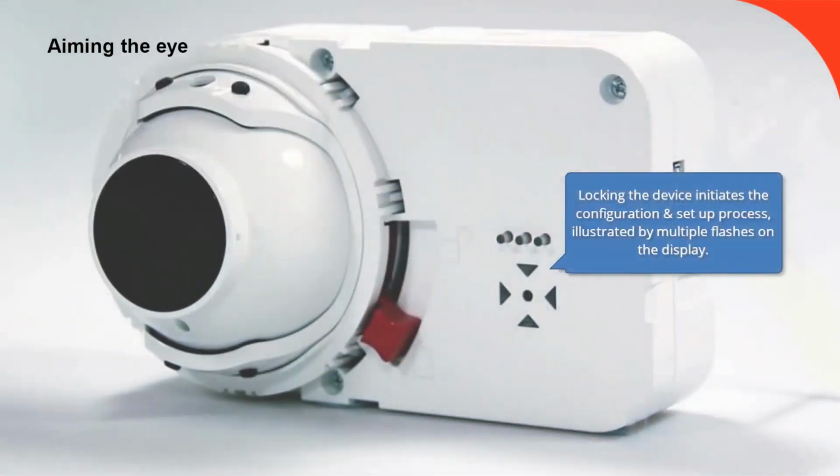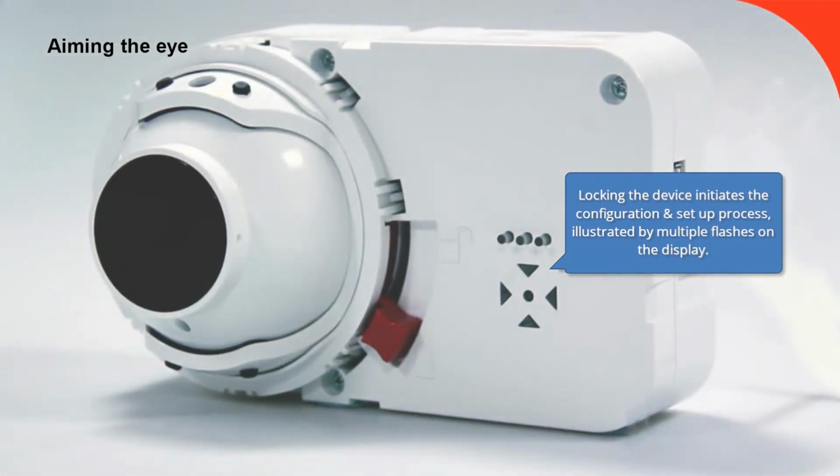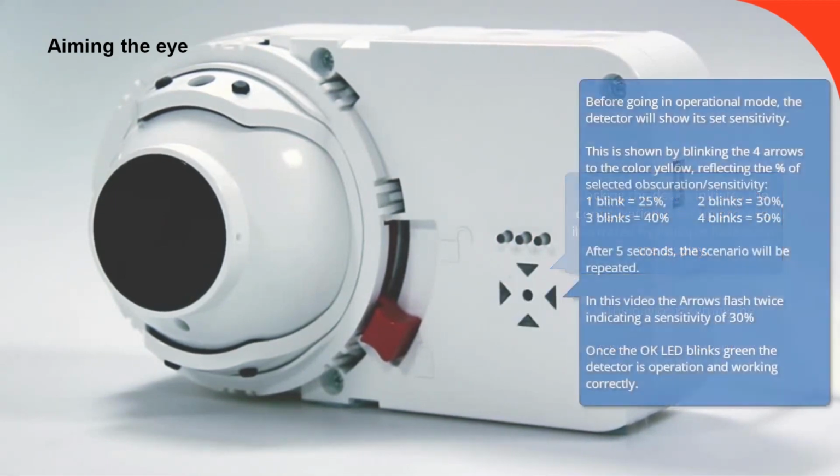The detector now goes through a short sensitivity configuration process, indicated by rapid flashing of the arrows. Once this process is complete, all 4 arrows will flash a number of times, then pause for 5 seconds before repeating the sequence of flashes. This number of flashes represents the selected sensitivity. When the green LED blinks, the device has completed setup and is operational.